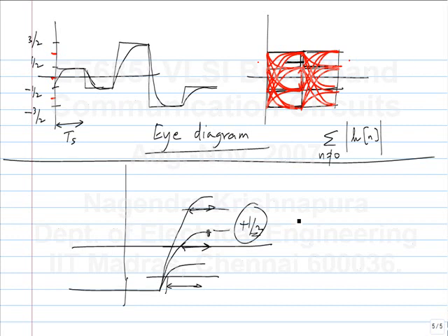Okay. So in fact that doesn't correspond to the middle transition, right? Because I would make sure that everything that is causing intersymbol interference is either plus 3 halves or minus 3 halves. So I'll have all these transitions and this one, that gives me the worst case.